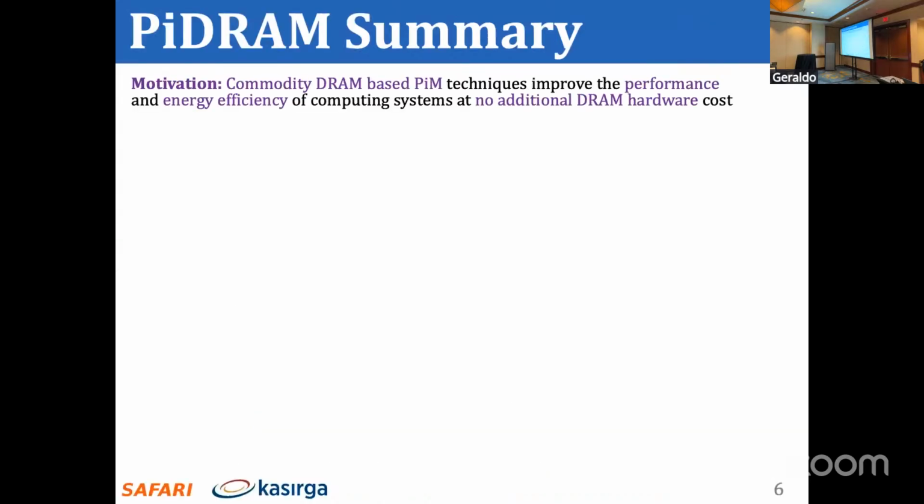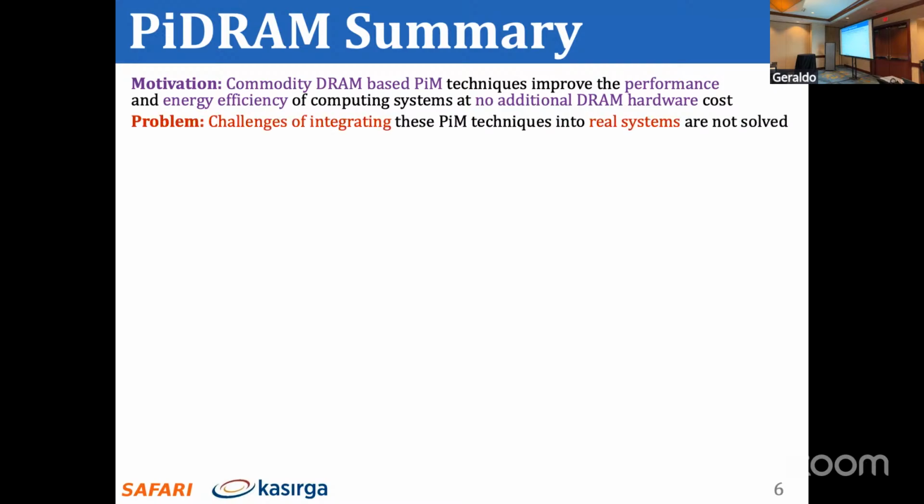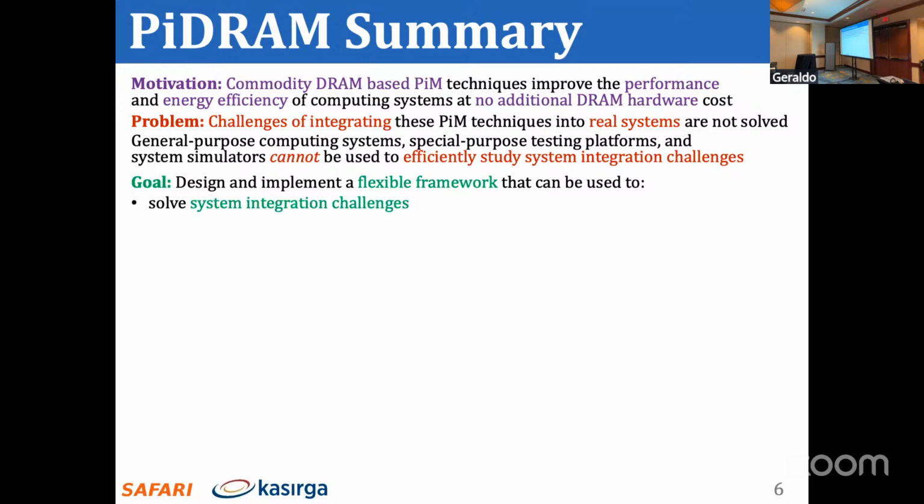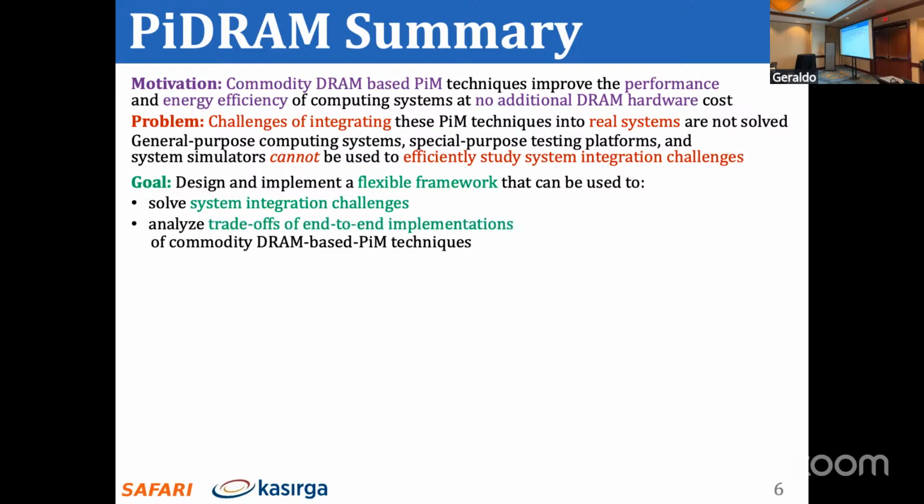So I'll start with a summary, but then I'll dive deeper into PiDRAM. We've seen a lot of commodity DRAM-based PIM techniques, those that we can perform in real DRAM chips. They can improve performance and energy efficiency at no additional DRAM cost, basically. But there are challenges of integrating these techniques into real systems, and we've talked about some of them. Our goal in this work was to develop a flexible framework that would allow us to solve these system integration challenges and evaluate them end-to-end in a real system.